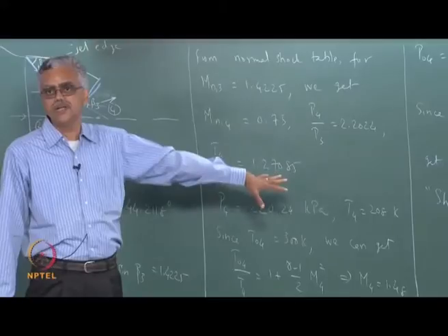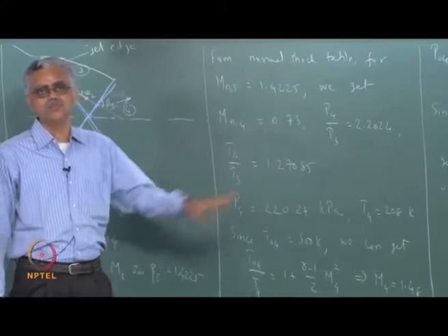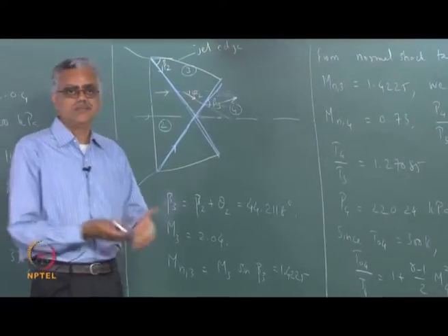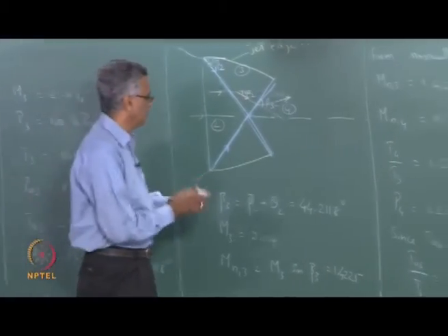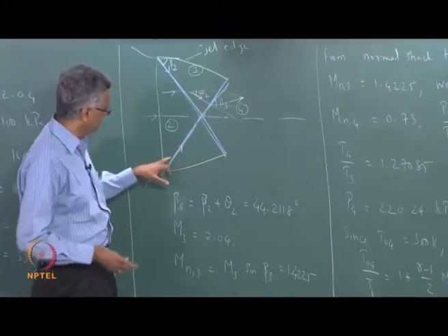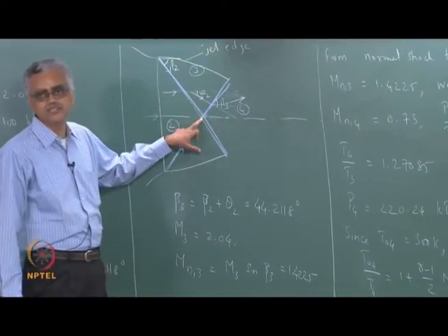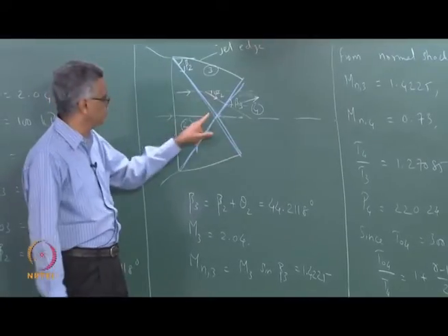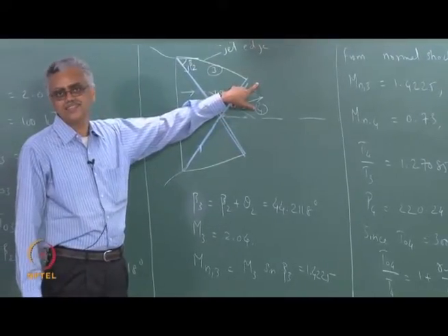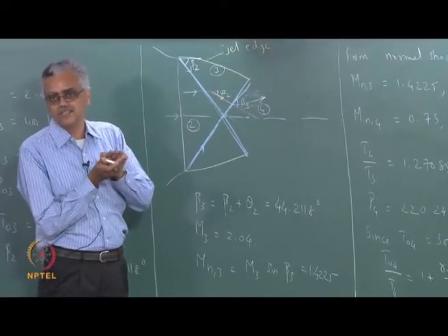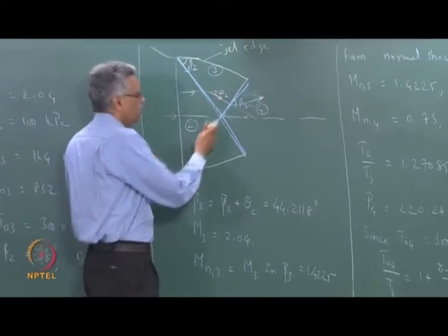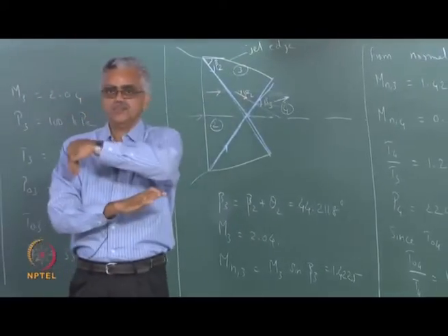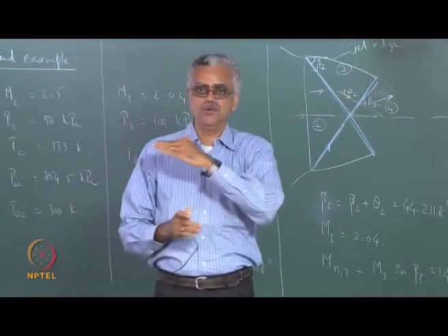Most of the quantities that we are predicting here will be almost the same as what you get from a much more complicated calculation. But the actual theory, what a complex theory would predict, is when these two shocks impinge upon each other like this, this one will reflect from that shock and this one will reflect from that shock. So the angles will be slightly different. This shock does not go through the other one, they do not go through each other. The first one reflects from that point, the second one reflects from that point.